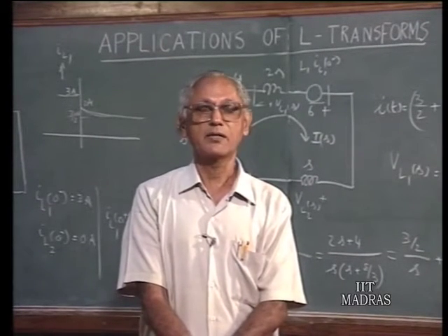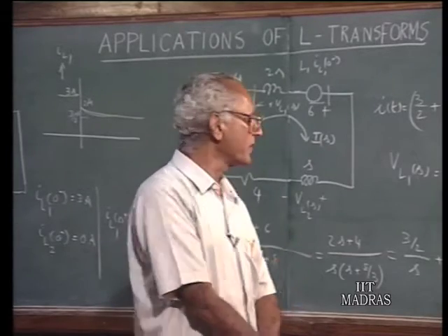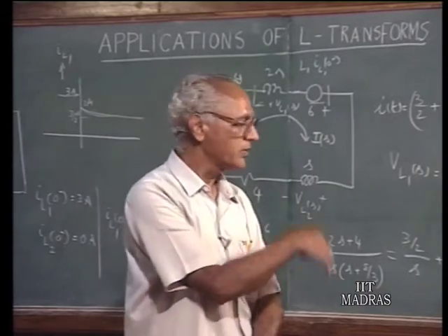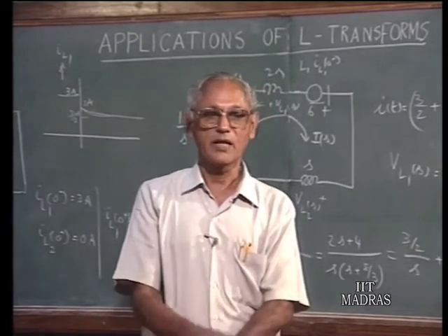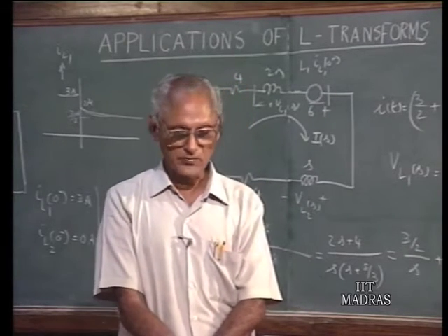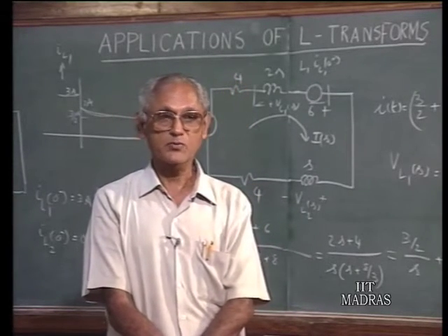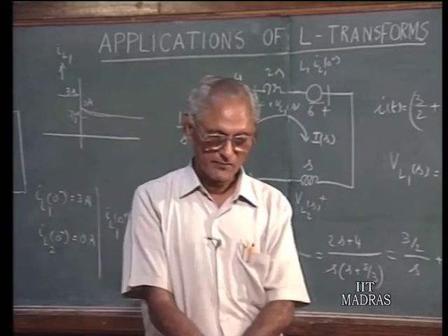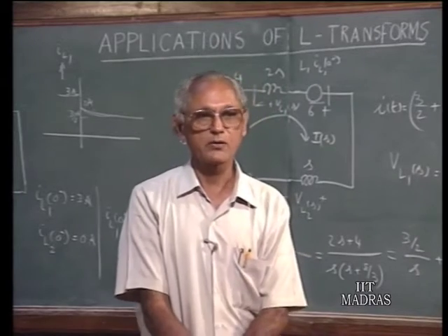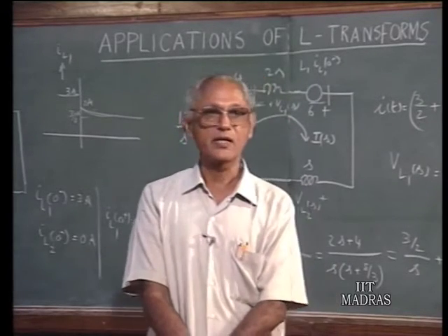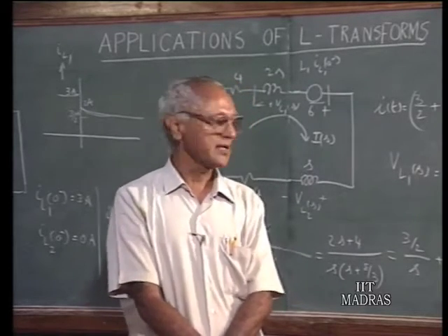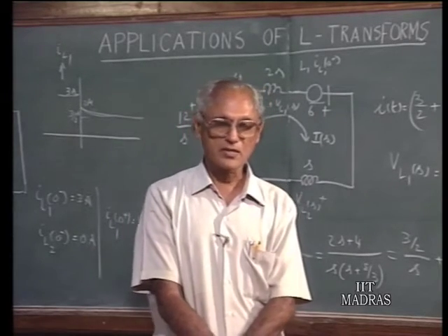And this is very important, because if the order of the system, the number of reactive elements, becomes large, suppose there are 4 or 5 reactive elements and you have a 4th order differential equation, then you need to know 4 initial conditions, not only the initial value but the values of the first 3 derivatives. And this becomes quite complicated because they are not evident, they are not given with the problem, and you have to calculate this. You have to find out the initial derivative, the second derivative, the third derivative through separate manipulations. All that is unnecessary as far as the Laplace transform technique is concerned.